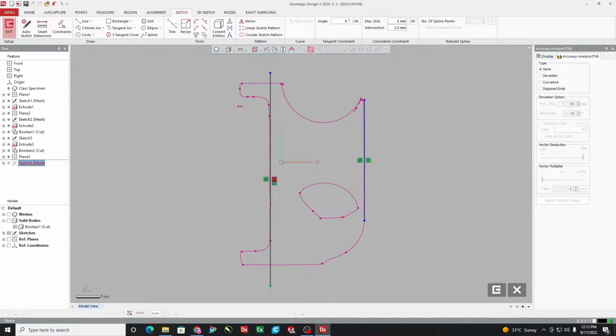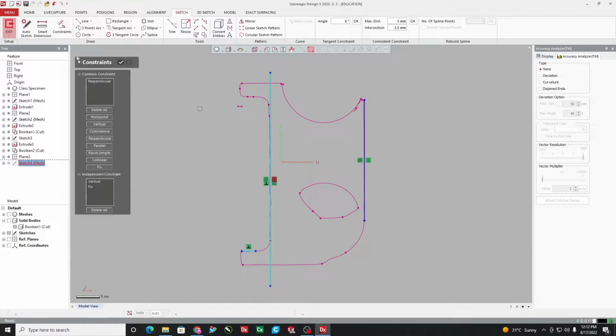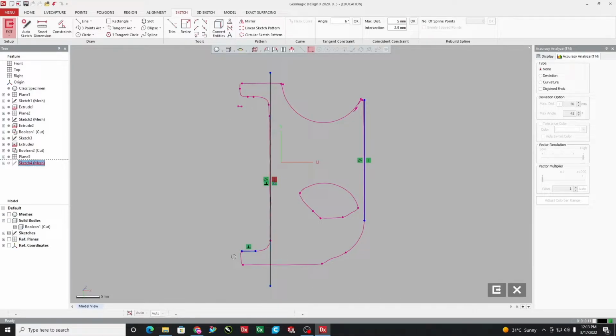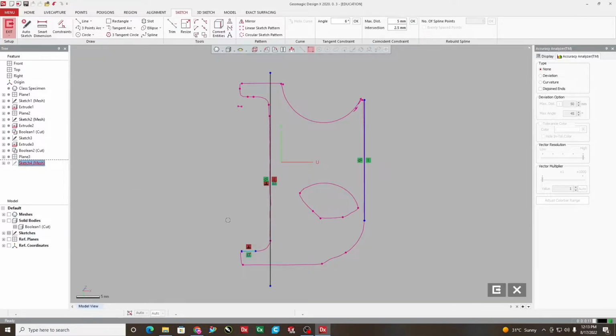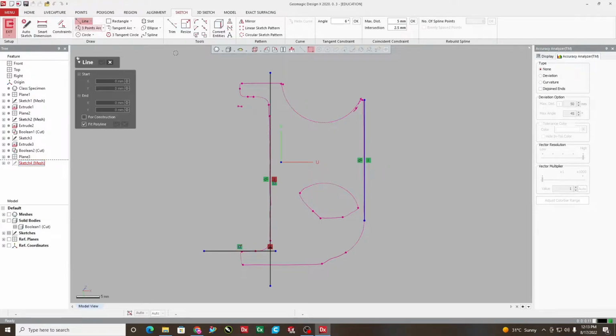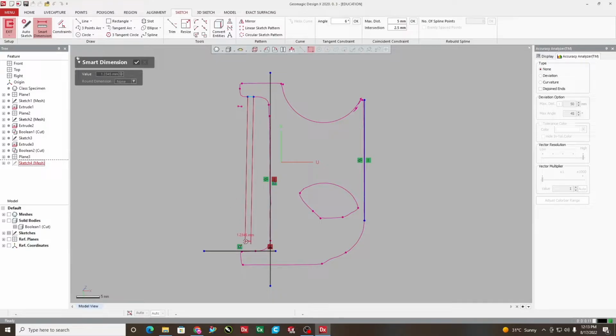To put the pocket, the actual depth of the pocket is to be taken, which was seen when we touched the virtual plane there. That was around 3 mm. So again I put the constraints here. To put the pocket, I need to have the boundary of the pocket, where the pocket is required. I now put the lines here, perpendicular to the line that is generated on the top. So this is made perpendicular to it. I've extended it so that I get it very clear. Again, a similar line is created between the two nodes up there. So these are again to be extended.